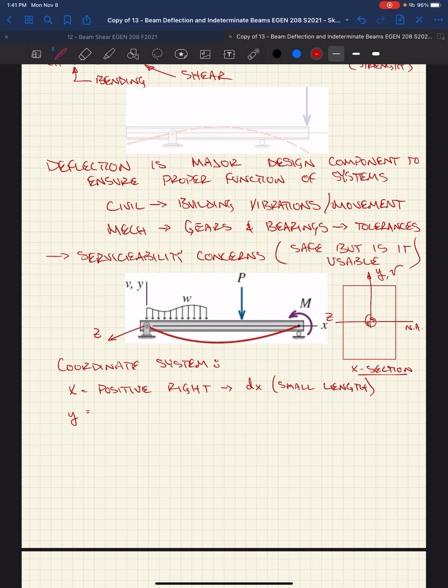Y, right, is our vertical axis, which really gives us the ability to describe our location within a cross section. Right, where are we at? We're doing this with normal stress in beams due to bending, right? Negative My over I, locating ourselves within the cross section vertically.